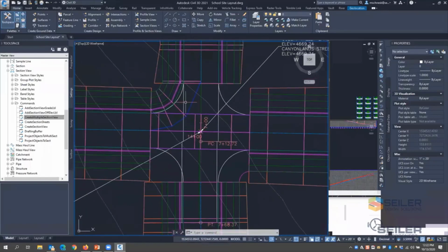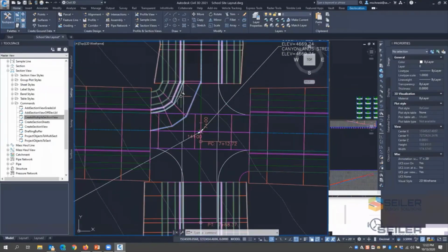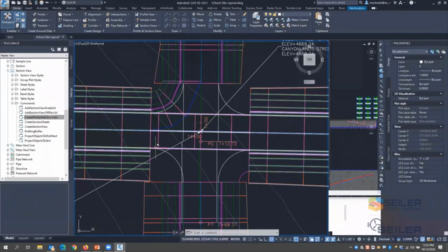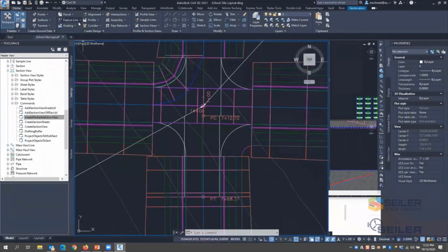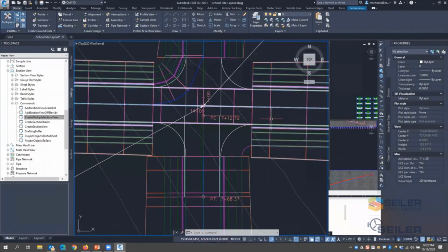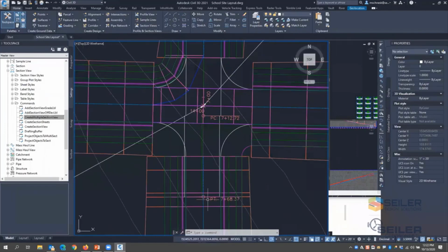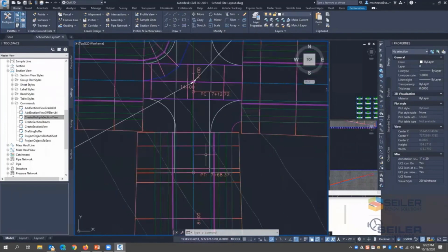When you do intersections and set up your intersections, you typically run your connected alignments, and then you'll set those up in regions. And one of the things you do when you do a region setting is select the corridor that you're adding your region to, which would be this one.